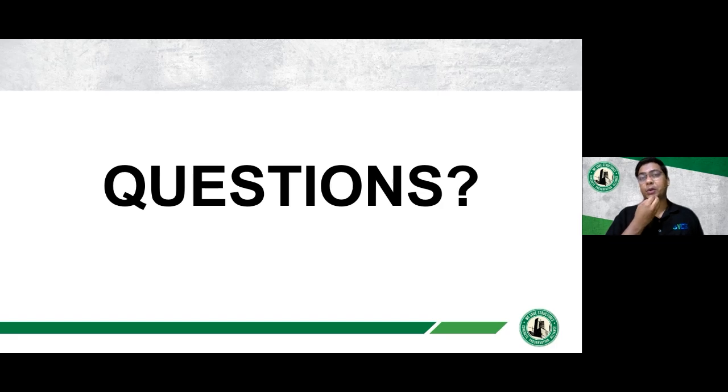This is a very specific question regarding the project. If I have more details on this project, I can reach out to the person who asked this, but if we have more data on the structure, we can definitely look into it. But again, impact echo and GPR could give you an idea as to if there is any debonding. It can spatially locate the debonded zones in those inverted beams, yes. If you send me more details, I'm more than happy to look into that.